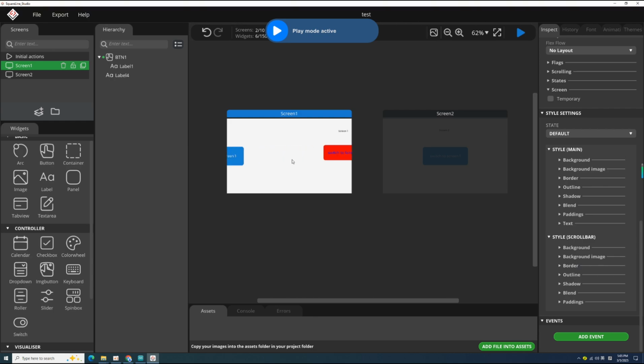And on screen 2, I can long press the button to switch back to screen 1. Since the trigger method for screen 1's button is release, it won't trigger if I hold the button down. It only triggers when I release it. As for screen 2's button, the trigger method is a long press, so no matter how many times I short press it, it won't trigger. Nice! This is exactly the effect I wanted.